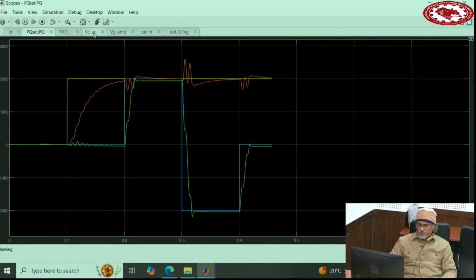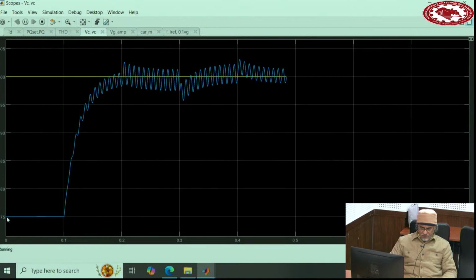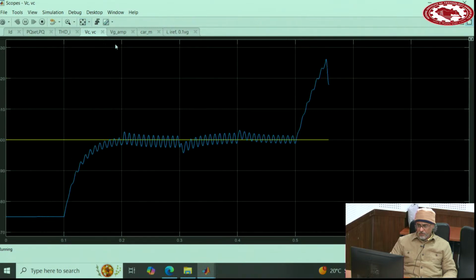So during all this stage, the capacitor voltage is this one. So at the beginning is 475, then goes to 500, and then remains around 500 as far as the power is full power. Here now it's going through the fault. Noises. And then fault is cleared, so comes back to 400, 500, sorry. And then the command of 500 to 520 is applied. It's up there.